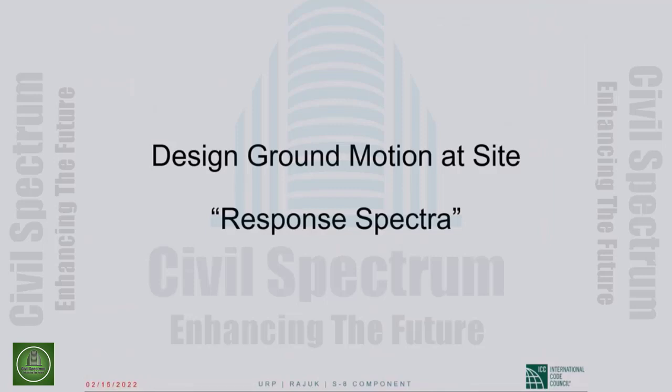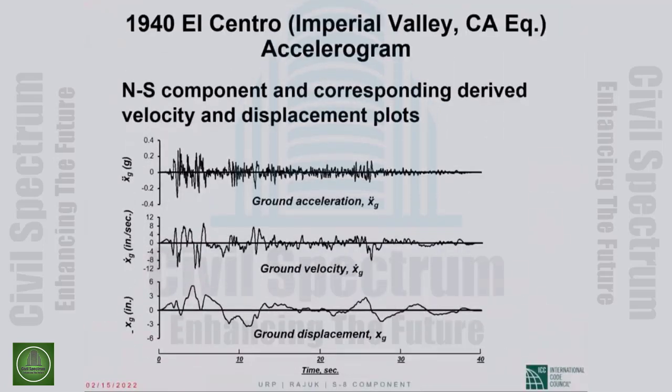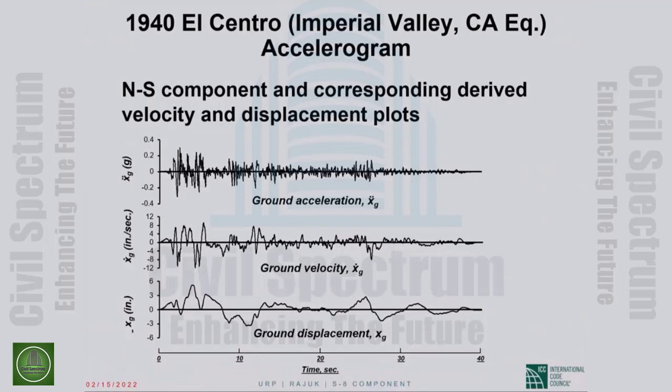The term has come up, and we have looked at spectra, but let's fully understand what a response spectrum is, and from that we will go to what we call the design spectrum. Now, the response spectrum is directly related to the design ground motion at a site. Design ground motion not at the source of the earthquake or somewhere else, but at the site on which we are going to build our structure, the structure that we are designing.